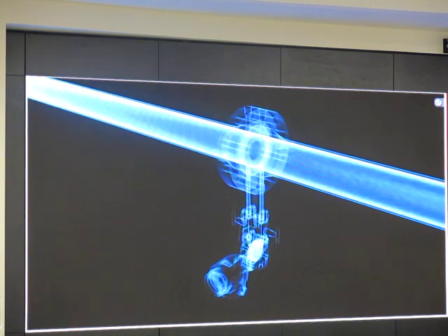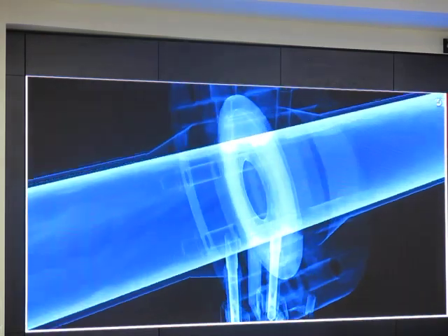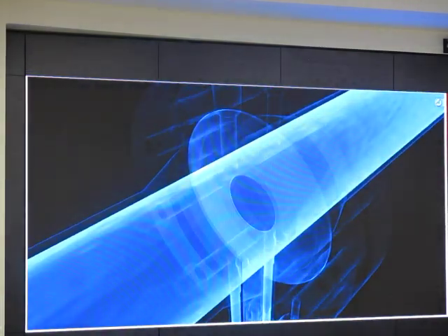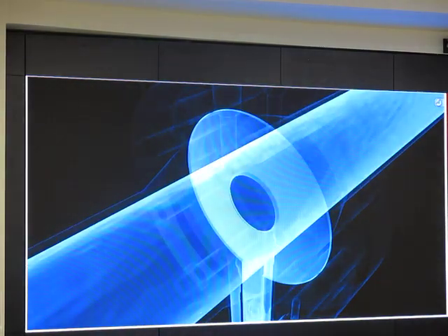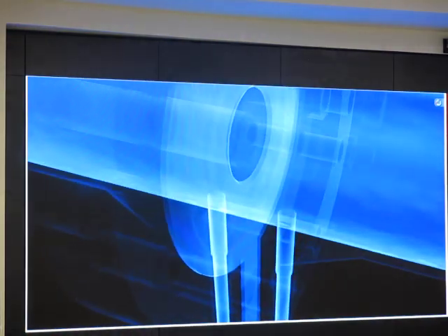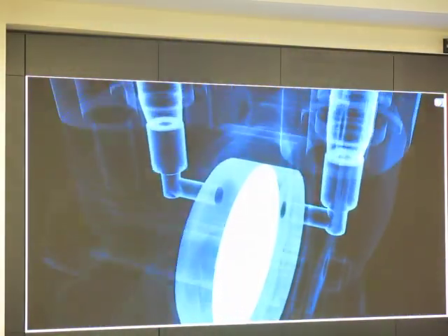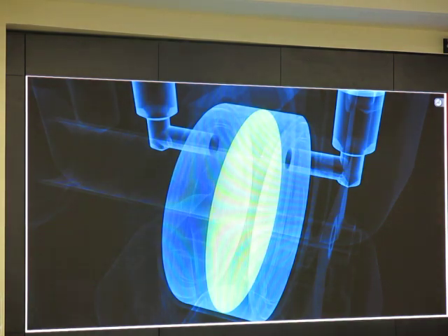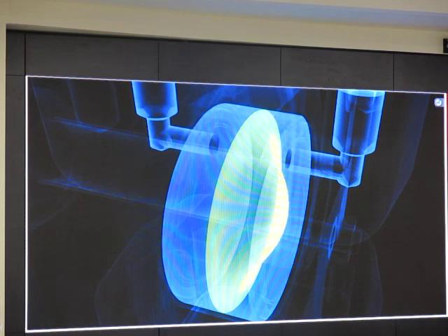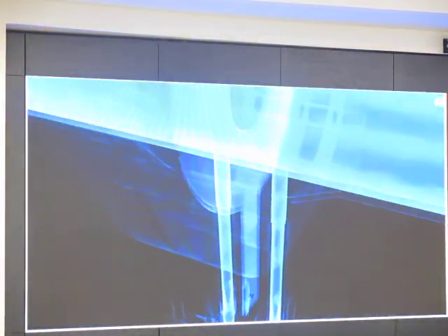Differential pressure flow meters have an artificial restriction integrated into the measuring tube, illustrated here by the example of an orifice plate. Two holes are located in the pipe wall, one before and one after the orifice plate. Two separate tubes connect these holes to a differential pressure sensor with its two pressure chambers, separated by a diaphragm. The tiniest pressure differences in the flowing fluid can be precisely measured.